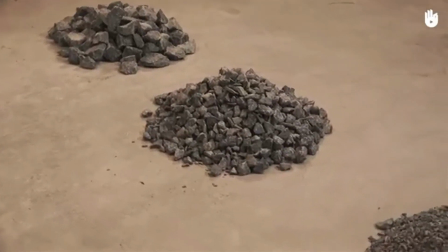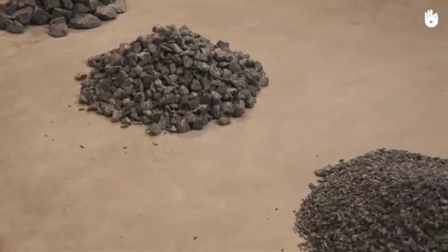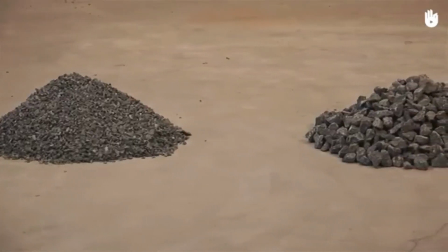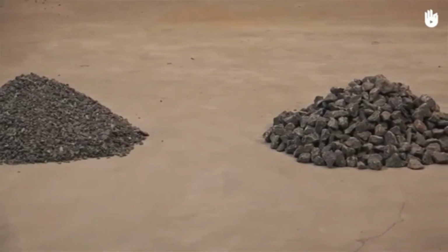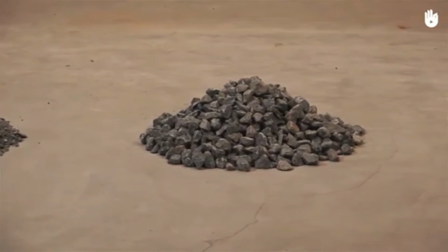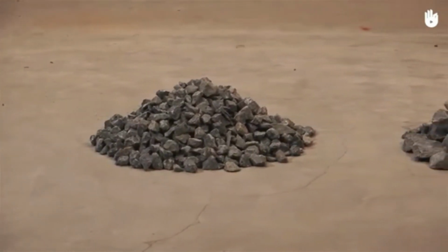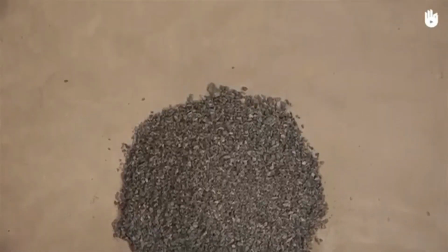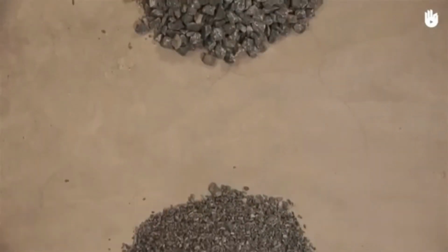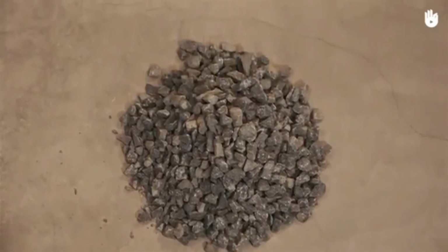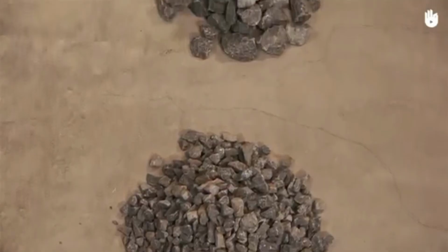Preparing coarse aggregates. Gravel or crushed rock is used for coarse aggregate. Gravel is found in natural deposits on the Earth's surface. Crushed rock is manufactured by breaking rock into pieces in a rock crusher. Pieces of crushed rock have sharp edges and may be shaped much like cubes. This is the best shape for aggregate. If the rock is too soft, it will crush into powder which cannot be used. Some kinds of rock break up into thin, flat pieces which also should not be used for concrete.